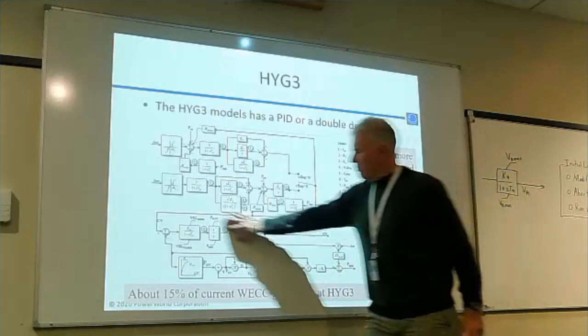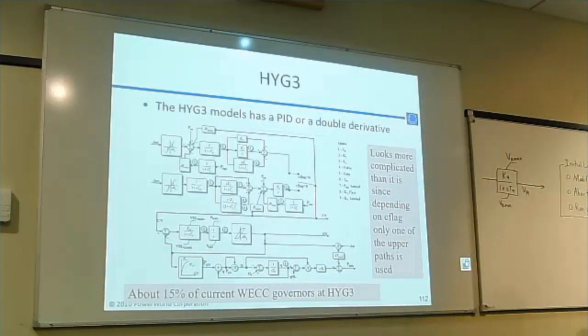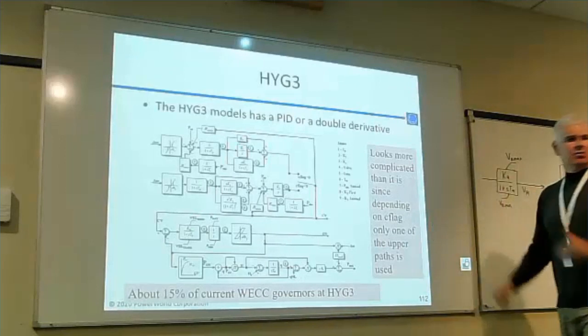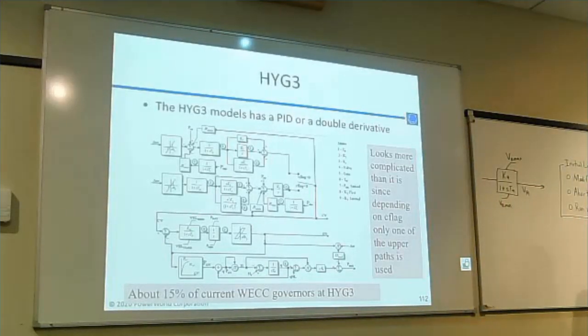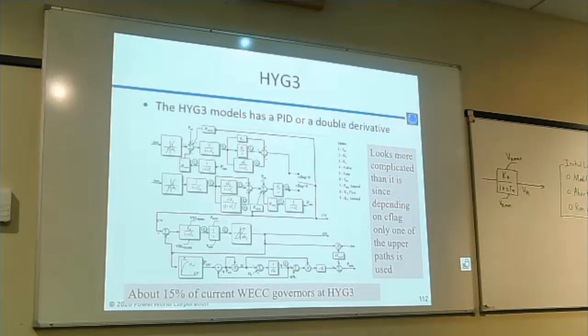This here is all modeling the plant itself, what physically is out there. You can't really change that once the plant's built. It is what it is. But this is a controller, it's a PID controller that you tune those values on to get the desired response. And as we just saw, if you set these values wrong, you can get an oscillatory response.